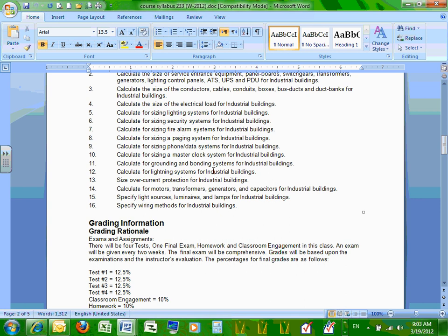What is a bus duct? What's a feeder bus duct? What's a plug bus duct? All this stuff, we're going to do it right in here. The system that we're using for this project, guys, is 480/277. So you get involved in a so-called separately derived system. You take a 480/277 system and you feed a 208/120 transformer to feed your receptacles. So how the transformer that I own and operate is going to interface with my service that's 480/277. So it's really cool. I think it's cool.